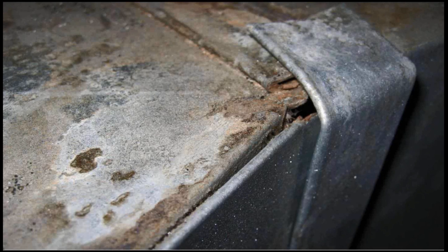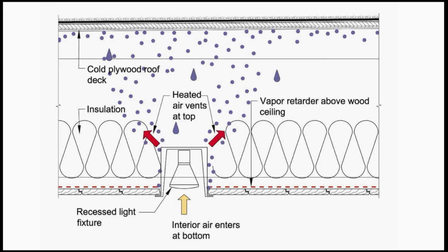It's a fairly typical joint that's not intended to be a real airtight joint, but even when we've done better levels of joining, there's still a problem when you put pressurized ductwork above the ceiling. So the air comes out of those and it puts moisture into the ceiling.